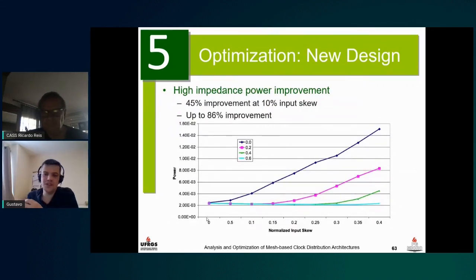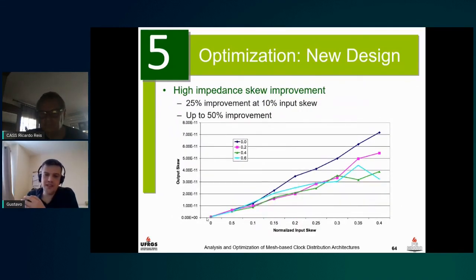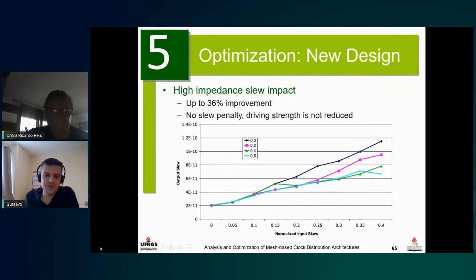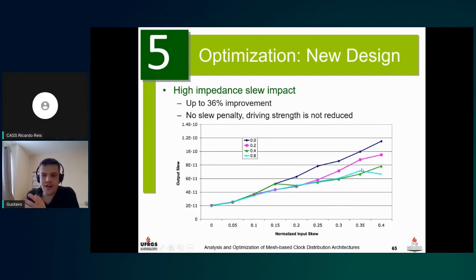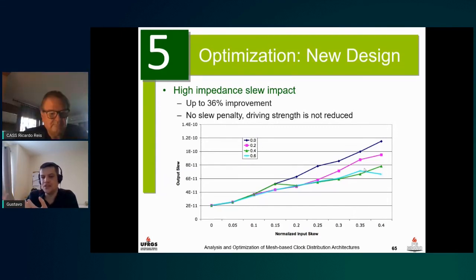but what ends up happening in the end is, let's analyze the clock slew. If we have a high clock skew at the input of the clock mesh, then the transition time at the output of the clock mesh is going to be determined by the short circuit current that is flowing through the buffers that are at 1 versus the buffers that are at 0.